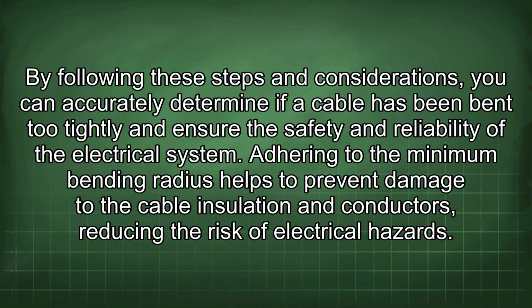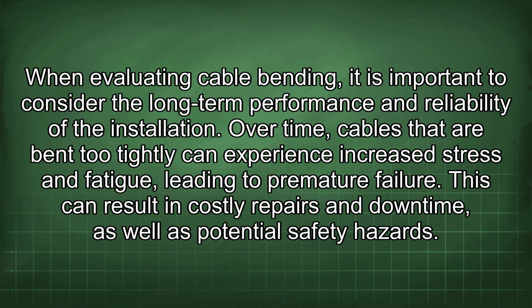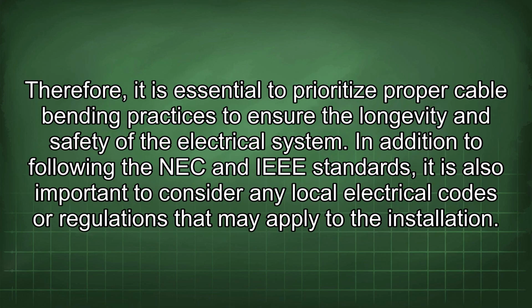Adhering to the minimum bending radius helps to prevent damage to the cable insulation and conductors, reducing the risk of electrical hazards. When evaluating cable bending, it is important to consider the long-term performance and reliability of the installation. Over time, cables that are bent too tightly can experience increased stress and fatigue, leading to premature failure. This can result in costly repairs and downtime, as well as potential safety hazards. Therefore, it is essential to prioritize proper cable bending practices to ensure the longevity and safety of the electrical system.